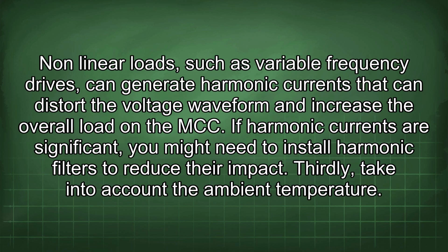Secondly, analyze the harmonic content of the motor loads. Nonlinear loads, such as variable frequency drives, can generate harmonic currents that can distort the voltage waveform and increase the overall load on the MCC. If harmonic currents are significant, you might need to install harmonic filters to reduce their impact.